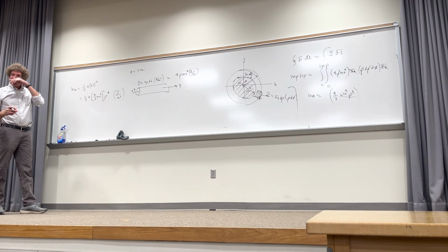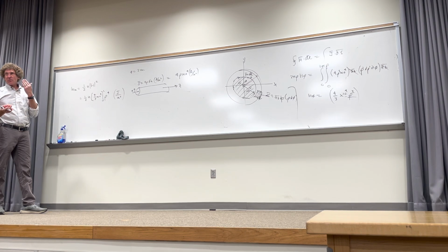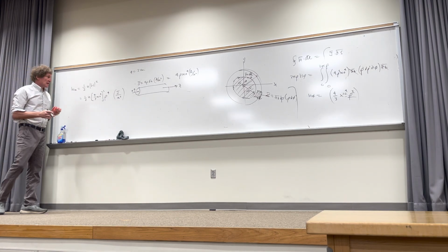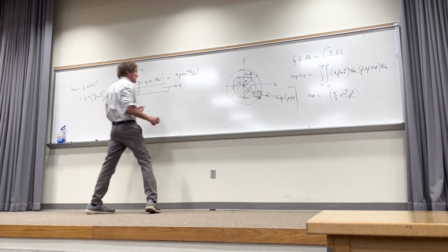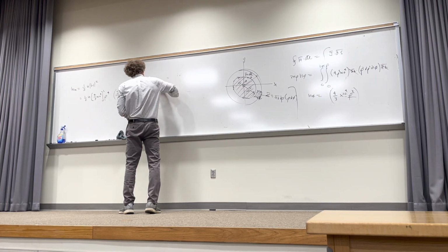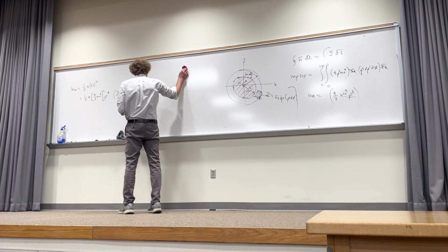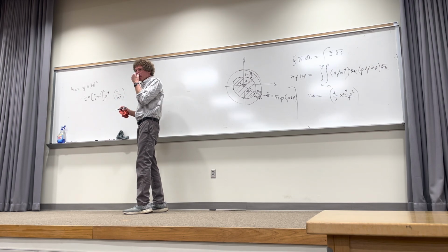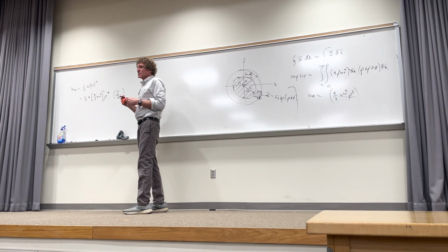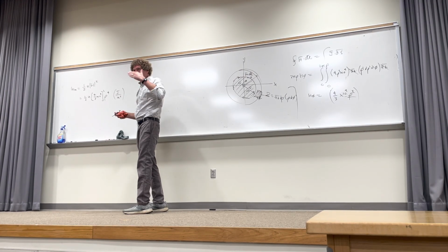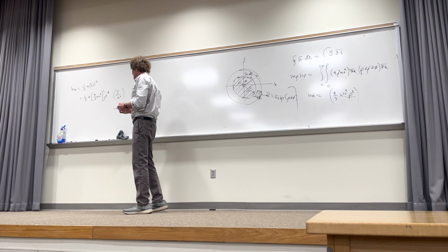Now we calculate the total amount of energy. That's the energy density inside the wire going from 0 to 1 meters in length, because we're going to do this per meter. So now, let me do it over here. Dr. Whitmer's book probably has this exact same steps. I don't remember. You can do this, it's tricky with flux linkage, but you'd be a fool to do it with flux linkage. If they have a variable current density like this, find the H field, find the energy density, and then do the energy density integral.